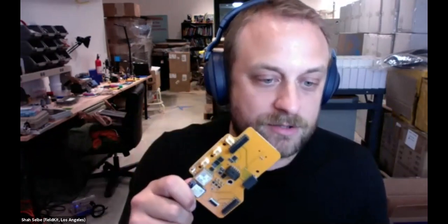First, I'll talk a little bit about the data logging part of our hardware. So we intentionally broke it up into two different boards. The reason we did that was because we wanted to make the ability for FieldKit to be upgraded very easy. And so this top board that has the screen on it has our microcontroller. Right now we're running an ATSAMD51 microcontroller, but it also has the SD card slot and all the memory and things like that. And we've separated out the charging circuitry and all the radios so that if you did want to create a FieldKit that used some kind of obscure satellite radio for some reason, you could do that just by spinning up this bottom board. You don't have to actually change the entire architecture of the device.